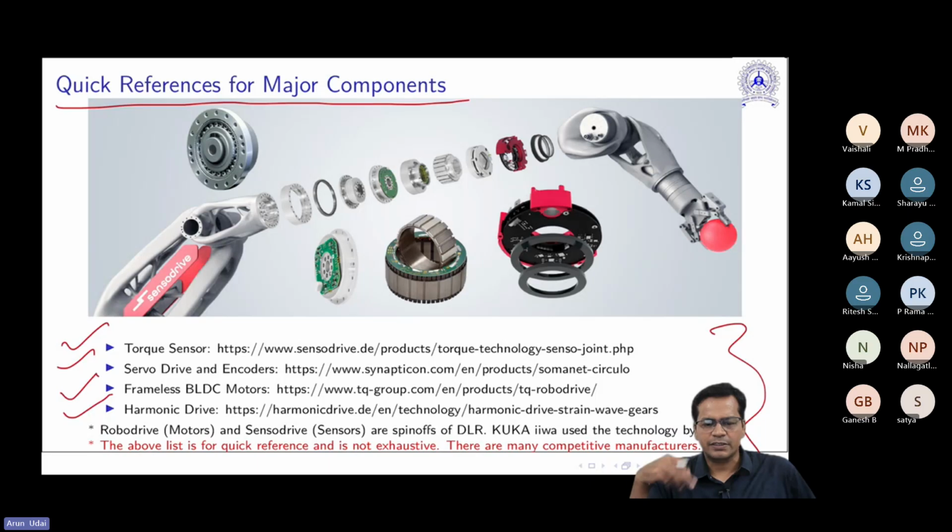You can create a servo loop and make a closed loop in position. But if you measure the current and control the current, you can control the torque also. So you can use a DC current chopper drive to control the current. With the same motor you can do it, and you can use a typical H-bridge driver with a position feedback encoder and create a closed loop.